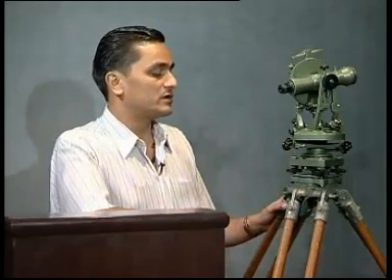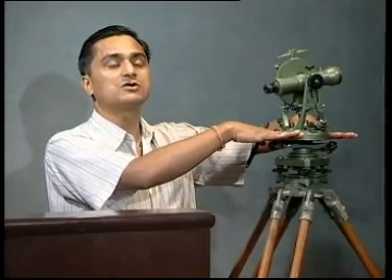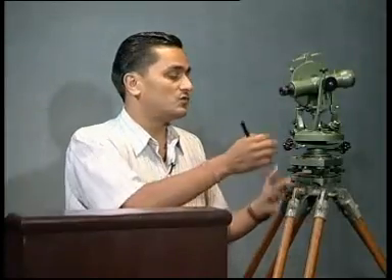Now in the errors in the theodolite, as usual, we'll talk first about the personal errors. How the personal errors will be introduced when we are doing the theodolite measurement. Okay, if you look at here, the observer, the surveyor, has not done the leveling properly. If the leveling is not proper, my horizontal circle is not horizontal. If my horizontal circle is not horizontal, what is happening? Now my graduated circle is inclined. So all the observations, all the angles which I am taking now, the horizontal angle, are not in a horizontal plane, rather in an inclined plane. Now this could be one error which can be introduced by the observer.